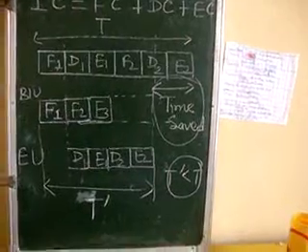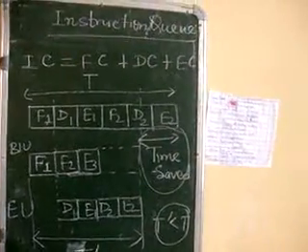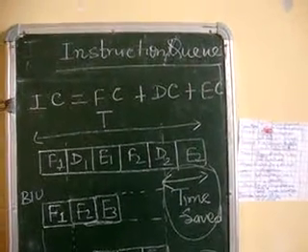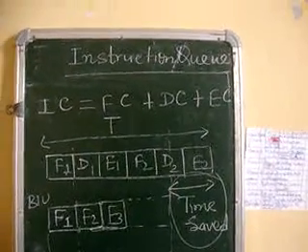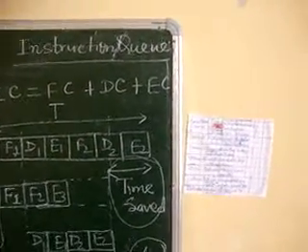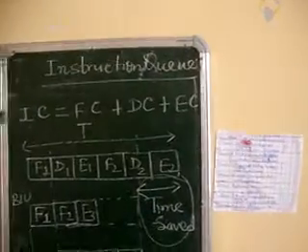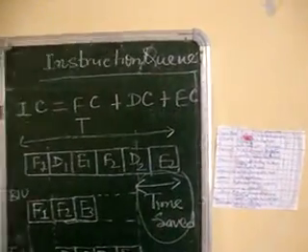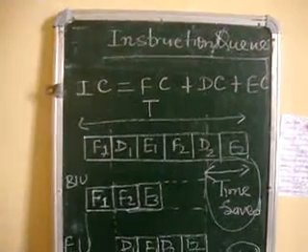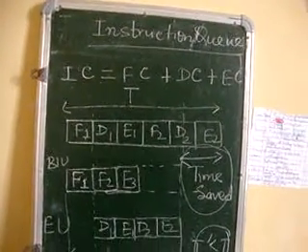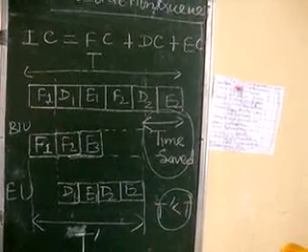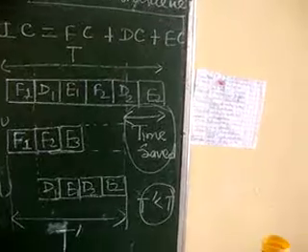Okay, so when you have to explain the function of instruction queue, the instruction queue is what? Instruction queue is a set of 6-byte registers which lies in the bus interface unit, where the pre-fetched instructions are placed before giving them to the execution unit. Due to availability of pipeline architecture, instruction queue can save much of the time and increase the speed of the processor. Thank you.